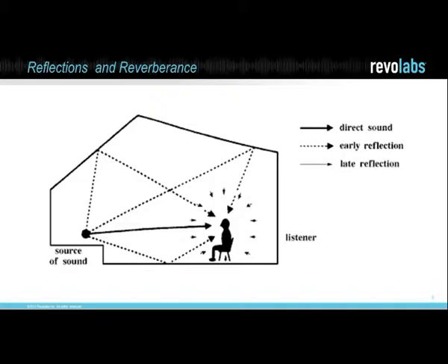I notice in this picture here, you're pointing out even ceilings are a problem. Is that correct? That's absolutely correct. So this illustrates some of the surfaces that would require acoustic treatment to be of an optimum design. If you have a ceiling that's of a certain shape, I have been in buildings where the designer made a very pretty looking alcove ceiling, but it was a disaster to have meetings under it. So absolutely, the shape of the room and the materials used is critically important.